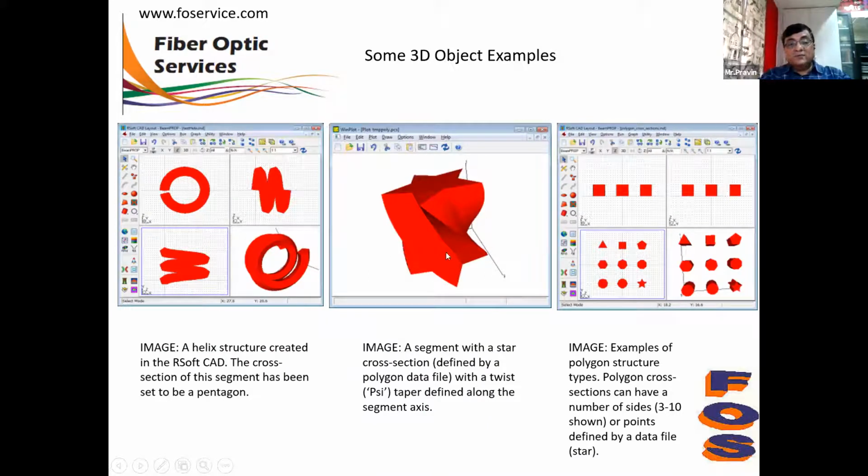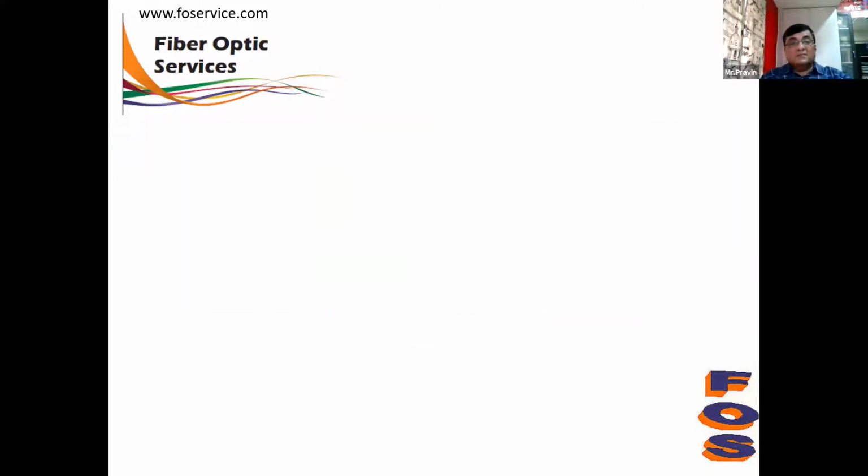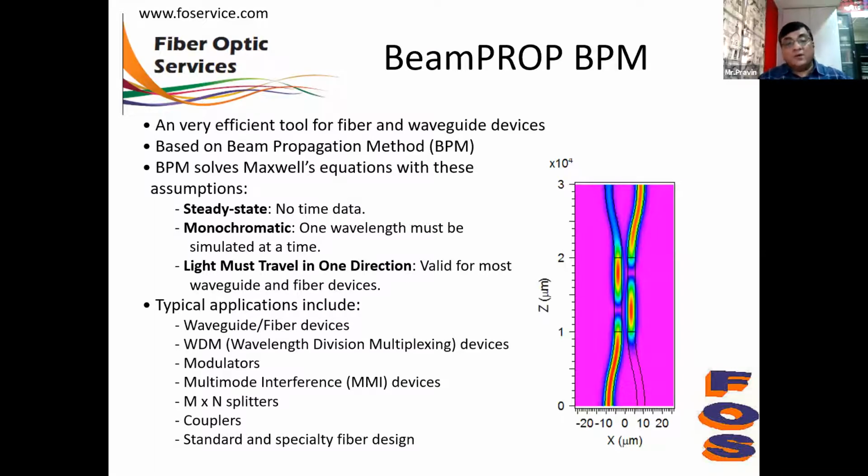As I have shown you, the different kinds of 3D objects can be simulated, or rather designed, in the RSoft CAD. Okay, so now next we move to the BeamPROP tool. BeamPROP is basically based on the beam propagation technique, which so many of you are aware of. It solves the Maxwell equation in a steady state with no time data.